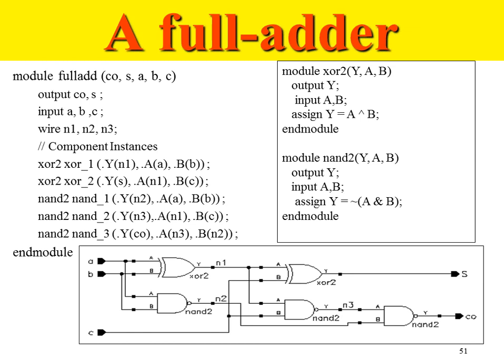Yeah, done. Okay, so one thing I would like to mention here is please remember that Verilog is a case sensitive language. So anything mentioned in capital, in this case, Y, A, and B are in capital, the port names, it has to be in capital where you are instantiating and doing the port mapping. You cannot have lowercase here, uppercase here, or lowercase here, uppercase here. That will not work. Whatever case you're using has to be consistent throughout the modules since Verilog is case sensitive.